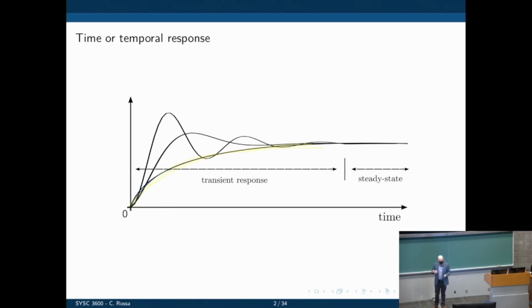But now when you deal with second-order systems, we have a second-order transfer function, a polynomial in the denominator of the transfer function. And that can now have complex roots, could have real roots, or could have a combination of them. So the shape of the time response may now take sinusoidal components, right? Because you remember that the complex part of the pole determines the sinusoidal component of any time response. So now we may have a combination of these two. So let's see that part today and focus on it.